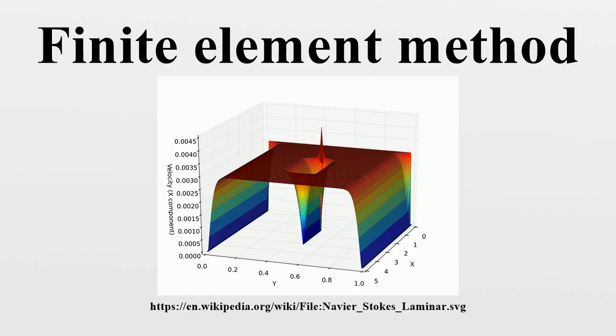The second step is the discretization, where the weak form is discretized in a finite-dimensional space. After this second step, we have concrete formulae for a large but finite-dimensional linear problem whose solution will approximately solve the original BVP. This finite-dimensional problem is then implemented on a computer.